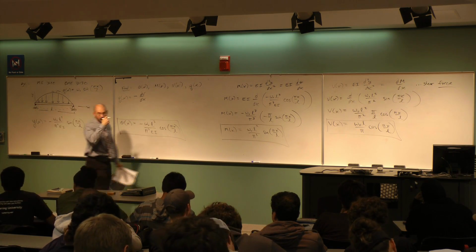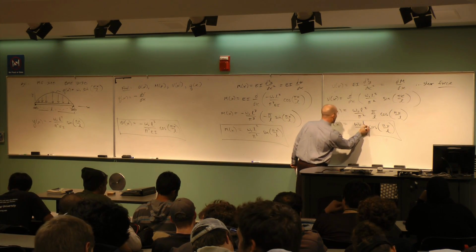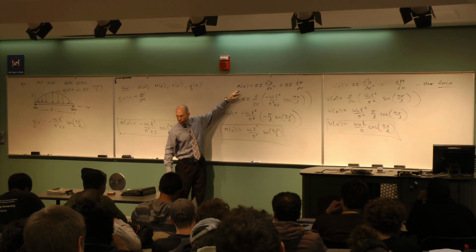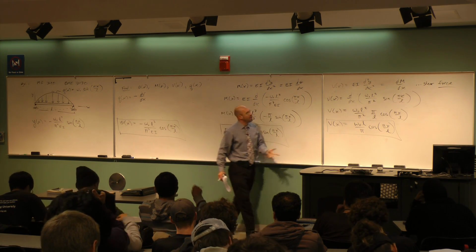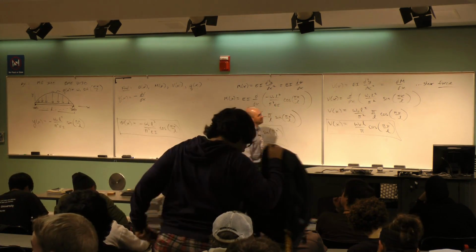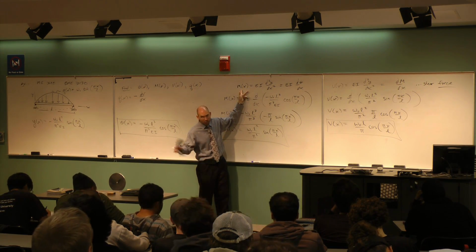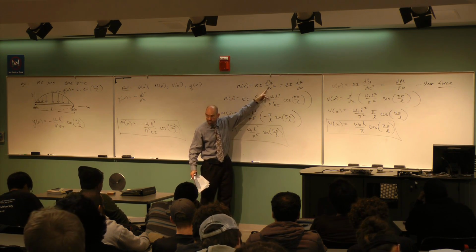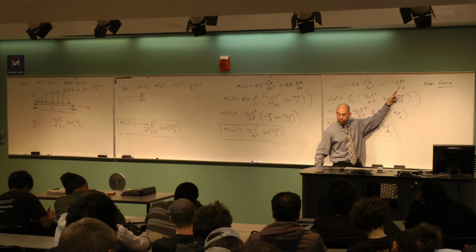Yes, question? Back to the x, aren't you supposed to multiply it by a EI at the end here? No, so let me back that up. I talked a little about that, but I know that can get confusing. By definition, the moment is the EI times the second derivative. The shear is the EI times the third derivative. Here's the moment again. If I just take the derivative of m, not multiply by EI, the EI is already there, and I get EI times the third. So this expression, EI times the third derivative, is just the derivative of m.